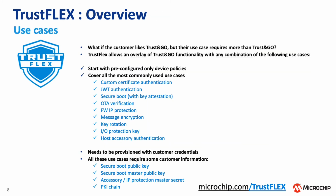So the TrustFLEX, what's inside? You can do certificate-based authentication, JSON Web Token authentication, secure boot with key attestation, OTA verification, and firmware IP protection. What this really is, is verifying firmware at different points in time of the system operation. Message encryption. You could do key rotation. We get that question quite a bit. The answer is yes, but to be honest, we rarely see it used because it has consequences in the backend infrastructure that are pretty complex to handle and expensive.